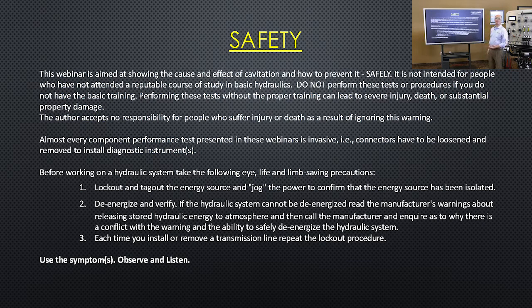Almost every component performance test presented in these webinars is invasive. That is, connectors have to be loosened and removed to install diagnostic instruments. Before working on a hydraulic system, take the following life and limb saving precautions. Always lock out and tag out the energy source and jog the power to confirm that the energy source has been isolated. In other words, follow your company's protocol with respect to lockout and tagout.